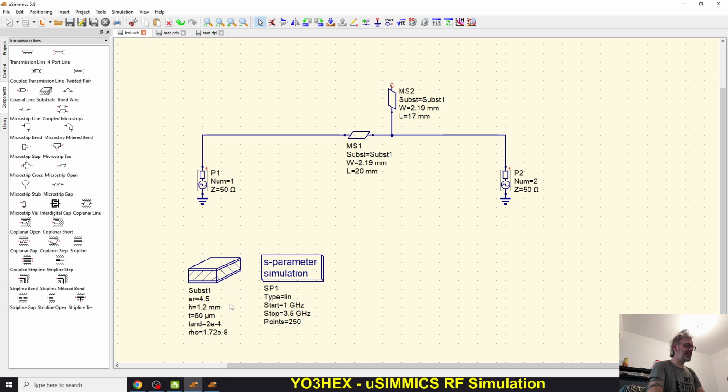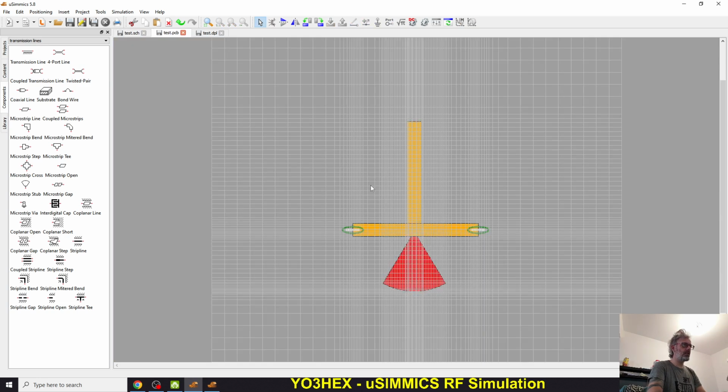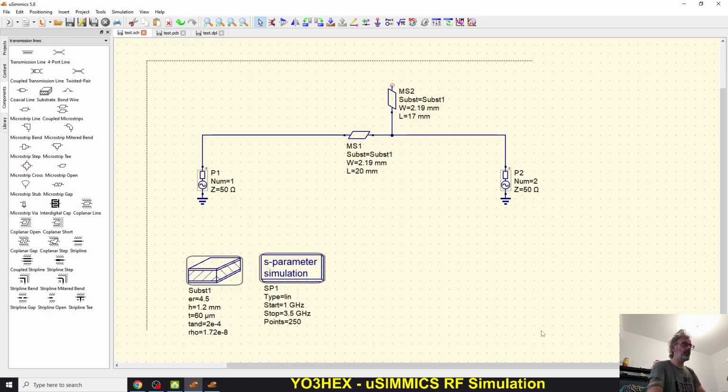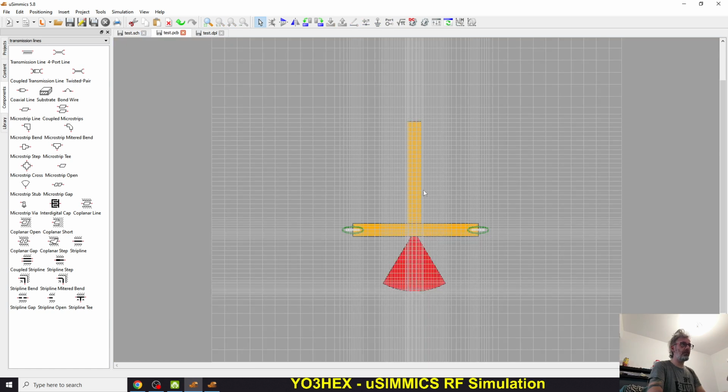You can run it without any of those parameters, but I think your system would be simulated against a Rogers substrate, which would not fit your need. That's why it's better to go from a schematic in which you define all the simulation parameters, and after that you can go on and modify your PCB and create various things in it.